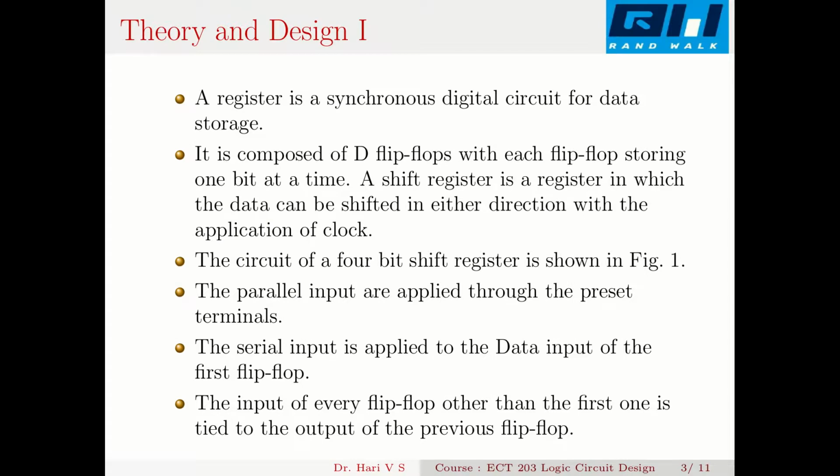So a register is a synchronous digital circuit for data storage. So the data is fed to a register and it is kept there. It can be serially or parallelly read out. So all flip-flops are clocked simultaneously. That's a synchronous circuit. It is composed of D flip-flops with each flip-flop storing 1 bit at a time.